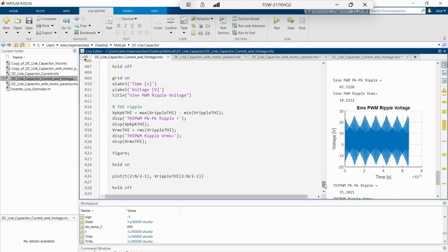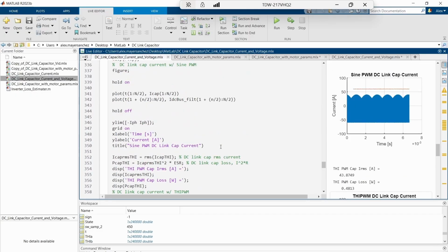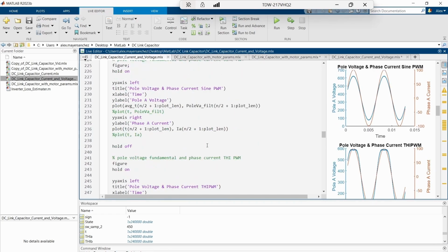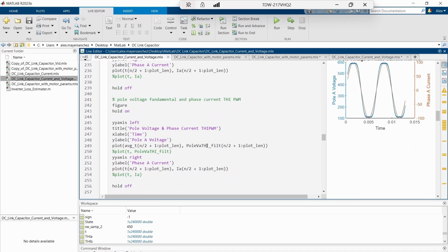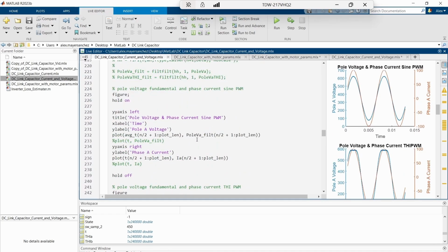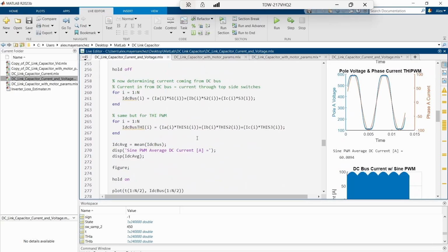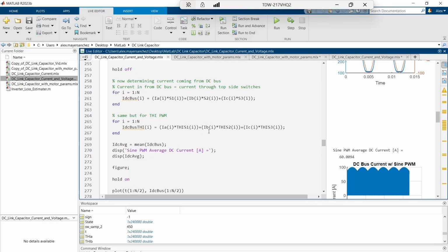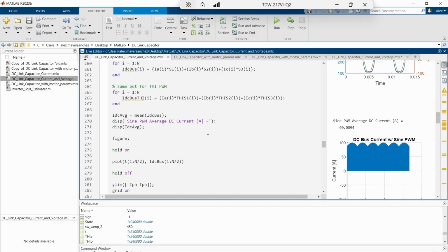Yeah, so basically, a recap of this video. In the previous video, we were able to determine the switching states of a 3-phase inverter based on the modulation index and the power factor. And then from that, we can determine what the current in from the DC link is instantaneously based on the switching states and having arrays for the switching state and the current in the load.